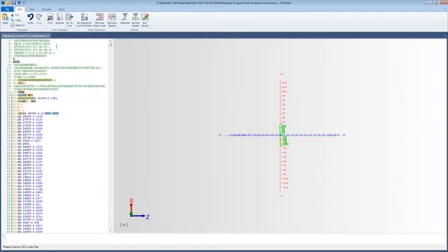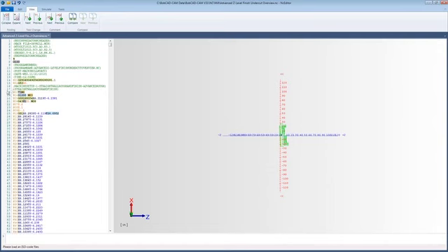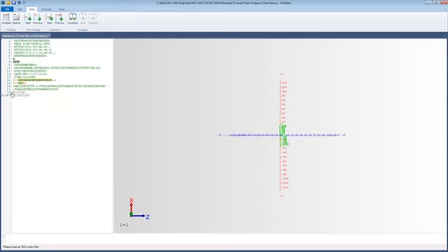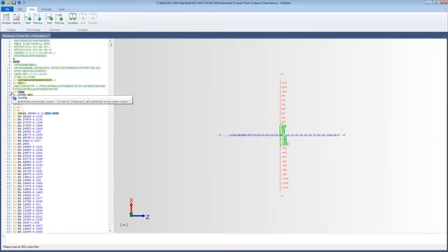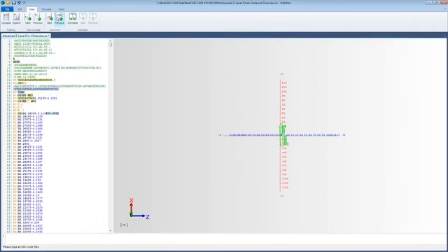The other page right here, we got view. This is going to let us collapse and expand these kind of breaks for tools. So it'll separate each tool anytime it sees a T1 or a tool call out. It might be the M6 it's looking for. It puts these little collapse and expand options on here, so you can collapse and expand those areas and see the code in between. Next is just going to take you from one tool to the next and kind of find the tools. Next, also finding any comments for you. So if you've left comments, you can look for them.